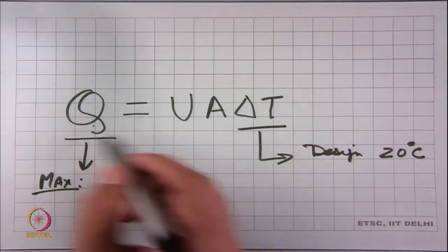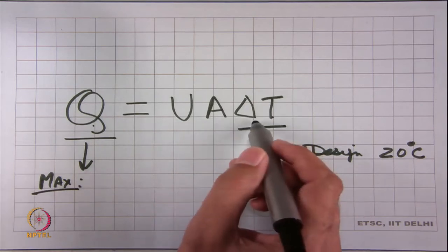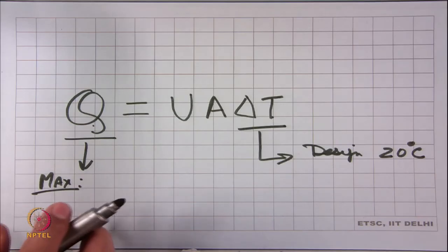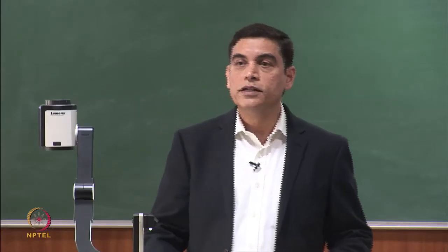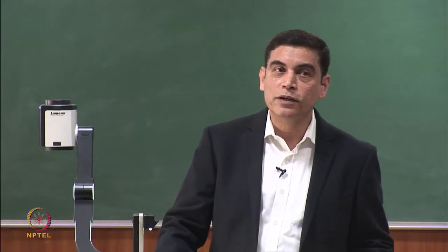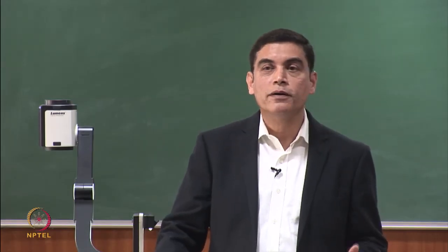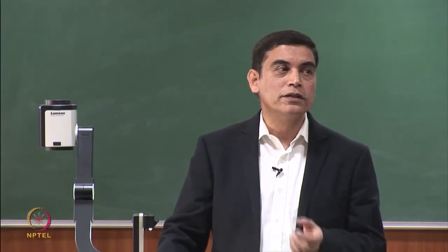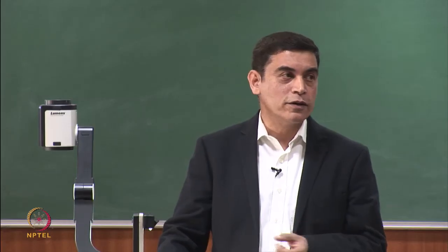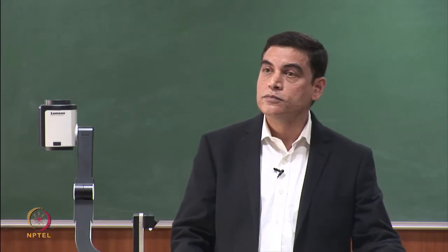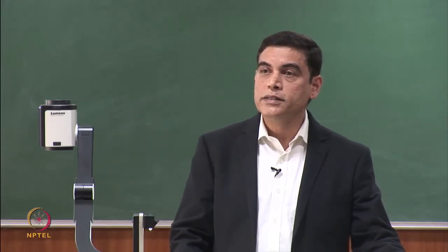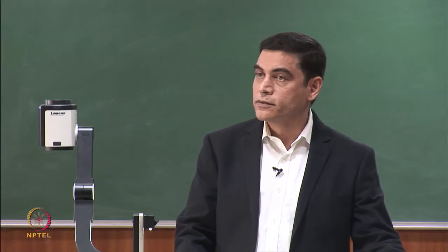When this comes down, the same heat transfer area will lead to a lower temperature difference to be able to transfer the same amount of heat. So, this is just one complexity as to how you begin to connect theory with the components that you are going to look at. And most of the time simple equations will not suffice. You will end up making a simulation program, having representative performance values of different components and connecting them together, proving them, and then you will be in a position to create something that represents an annual performance rating.